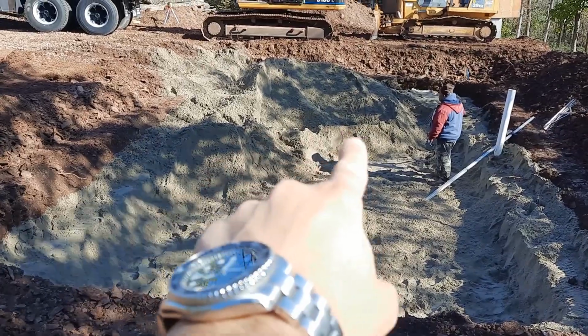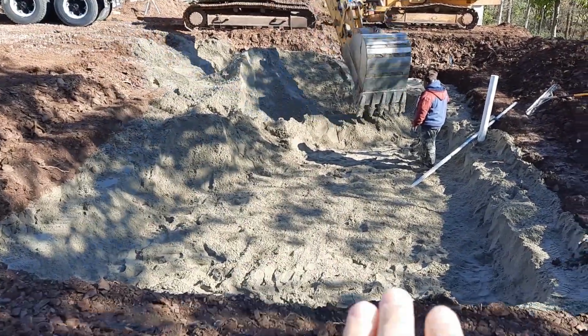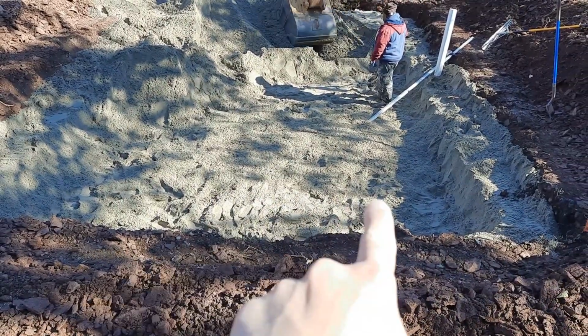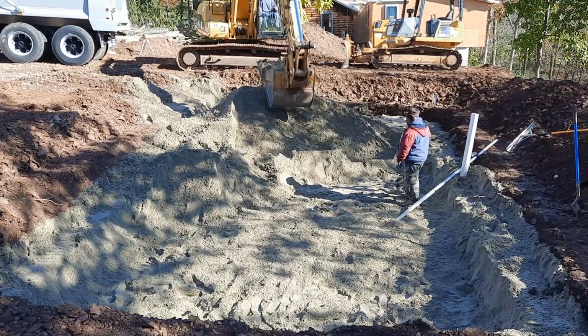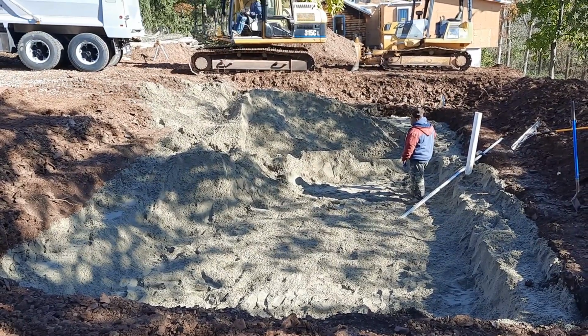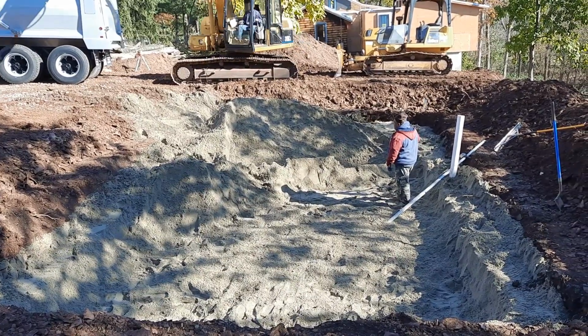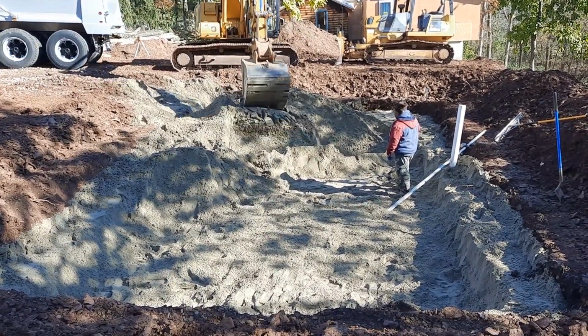There's excess sand over here. We actually have a little bit too much on this project, so they're taking some of it out, but they'll level everything to be even with this, and that's the top of sand inspection. That's what you're looking for. After this, they're gonna put the stone on top along with the laterals, and you know, we'll inspect it once they connect everything and take a look at it then.